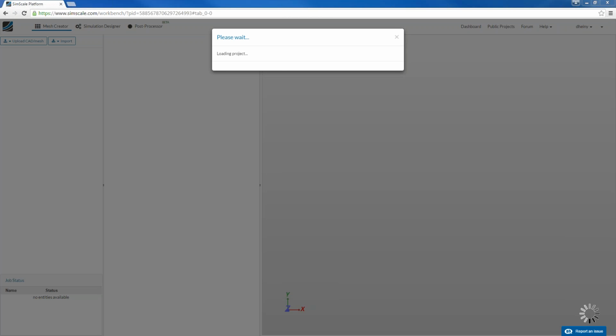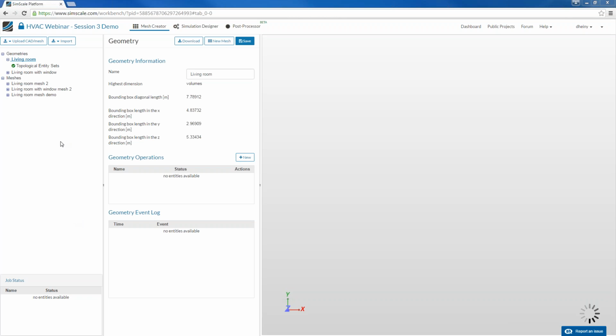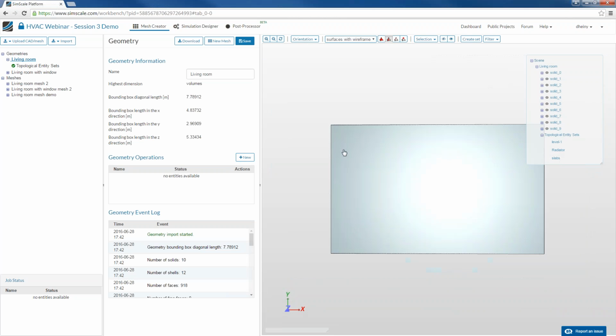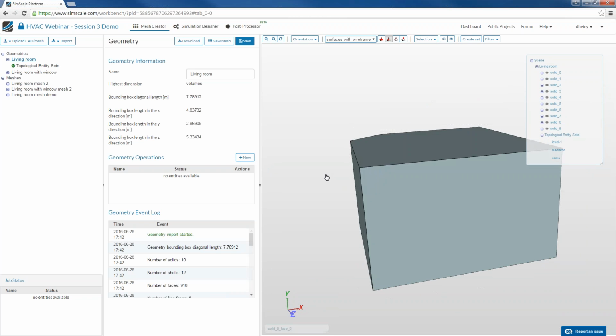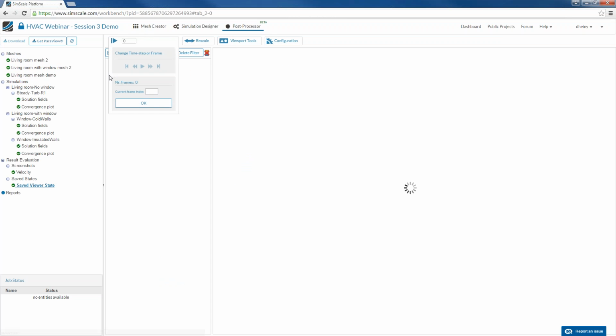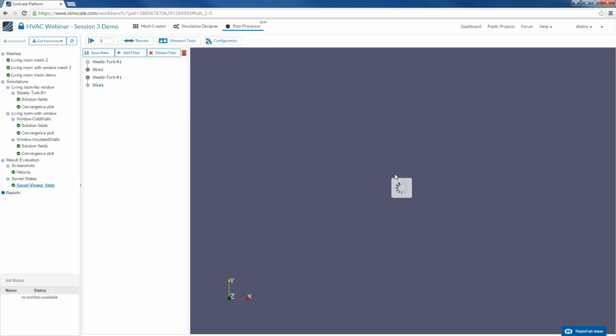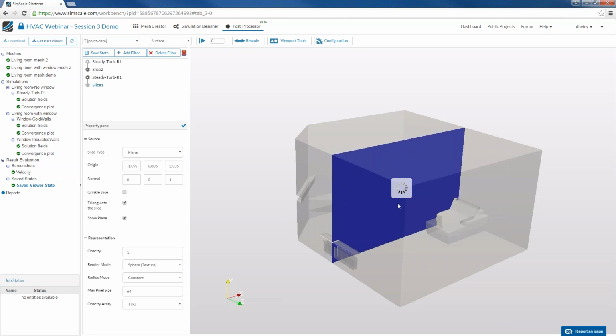I'm sorry that it takes a bit longer, but I just want to make sure that we've seen once the complete workflow. So we've seen the mesh generation, we've seen how the simulation was set up with this very simple scenario, but more complex scenarios will work essentially with the same workflow. You would use other boundary conditions, you might use other initial conditions, but the work is essentially the same. Okay, and once this comes back, you then can tap into the post-processing tab, which allows you to analyze, visualize, interrogate the results of your simulation. And I also want to make sure that you have a feeling for this as well, that you've once seen the entire workflow of SimScale.